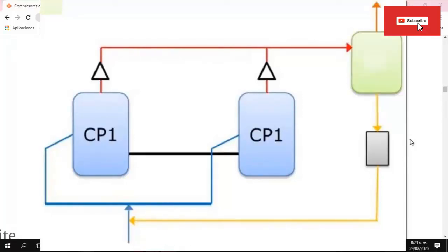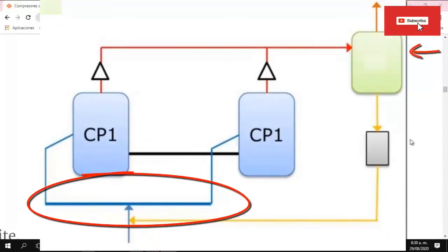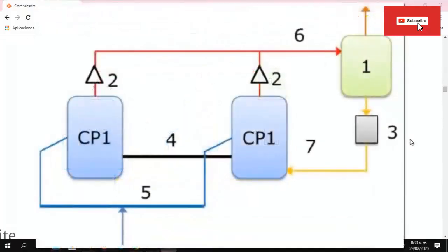12. This configuration places a strict requirement on the selection of the size of the equalizing oil line and design of the suction head. 13. The oil separator must be efficient for both single compressor operation and two compressors working together. 14. Requires strict suction piping design.